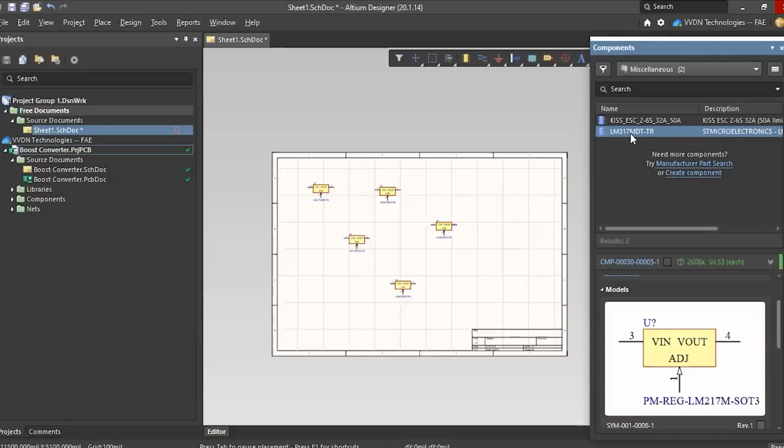Now this is related only to a single component, and we usually deal with many components in a single project. So if I want to manage multiple components in my project using Altium 365, we can directly migrate our library using the library migrator. We have the library migrator option, so I will show how to migrate the library.